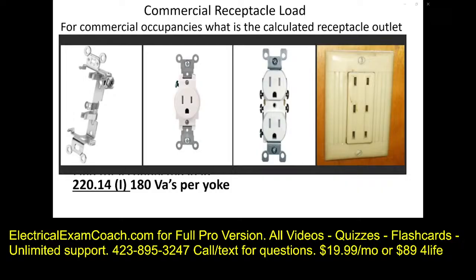This is a yoke. Starting on the left-hand side, it's also a device strap. It's what holds all the pieces together. What this code is stating is that whether we have a single, a duplex, or even this old school triplex here, each one of those would count as 180 VAs each. I like to think about it as each gang counting as 180 VAs.